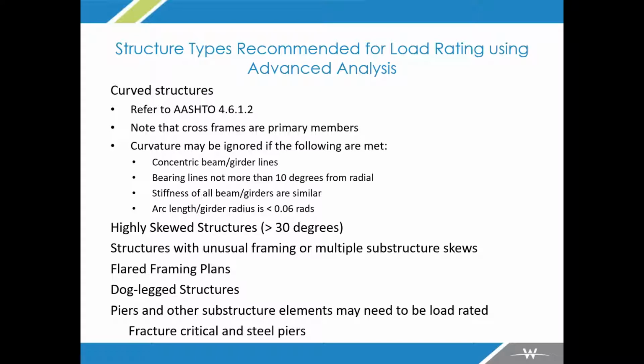Dog-legged, which is another treatment. Instead of doing a curved beam coincident with your curved deck, you might do, and particularly older structures often do this, a dog leg where it kinks throughout the system. And then sometimes you need to load rate things like piers and substructure elements, particularly fracture critical steel piers. You refer to the MBE, and it'll tell you when those are warranted. But that can be something you may have to get into as well. It's not just load rating the superstructure, but the substructure as well.